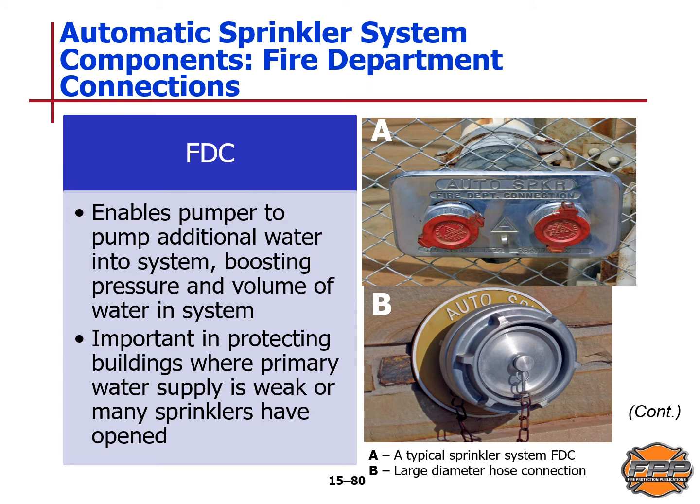This is an example of a fire department connection. This enables the pumper to pump additional water into the system, boosting pressure and the volume of the water in the system. This is important in protecting buildings where primary water supply is weak or many sprinklers have opened.